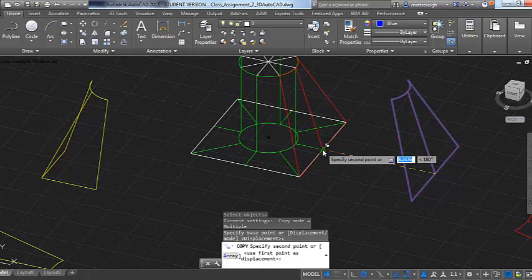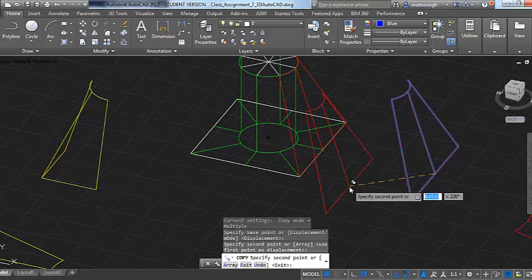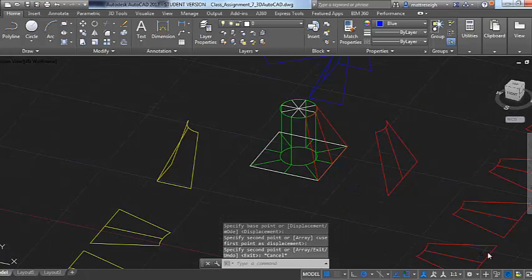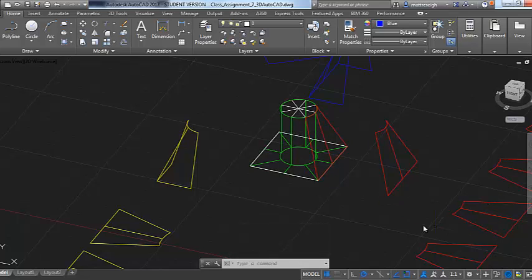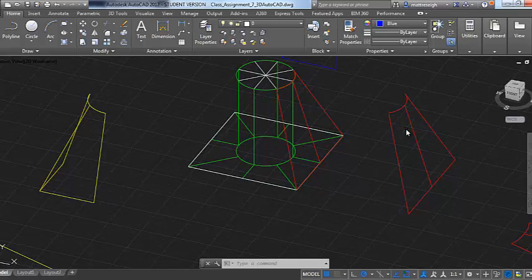I'm going to drop this in place now so you can see this. I've just taken that part, and I'll show you how to draw the flat pattern for this, not exactly in this 3D model. In this particular model, it shows that it's been formed up. This is what I just dropped on here. This is the center line of my pattern, this initial line, and the outside edges all become weld seams. It would take 4 of these going around to complete this part. It would put a weld seam on this thing that I've got highlighted right here, a weld seam right in the corner.